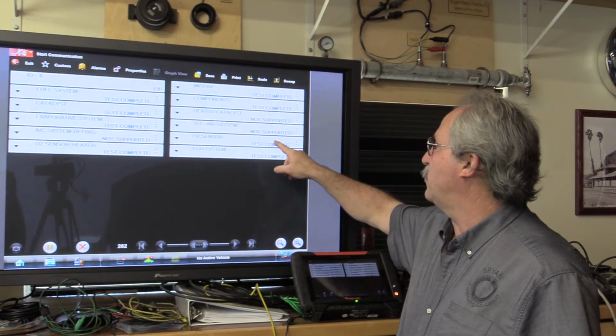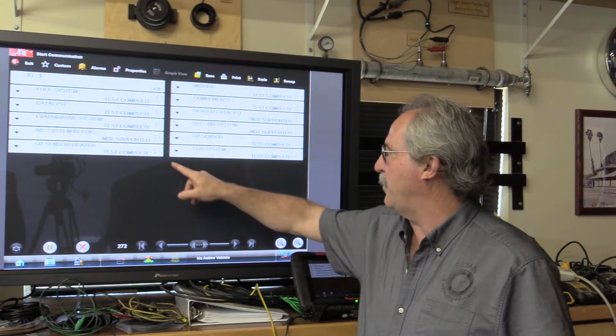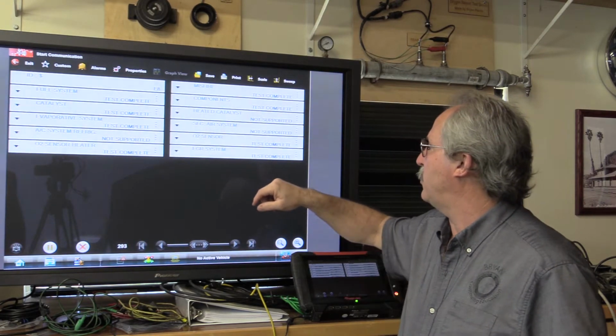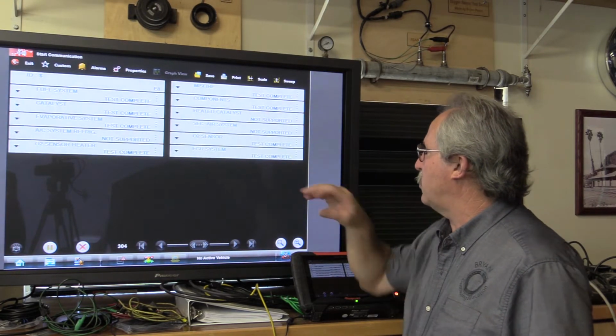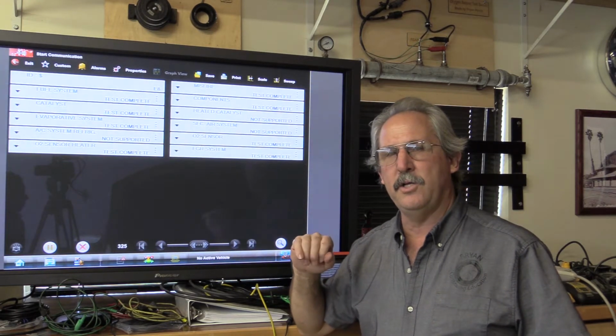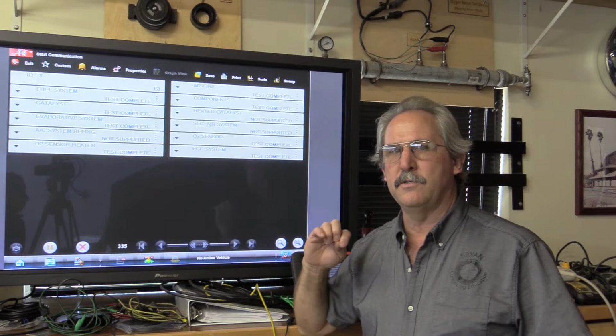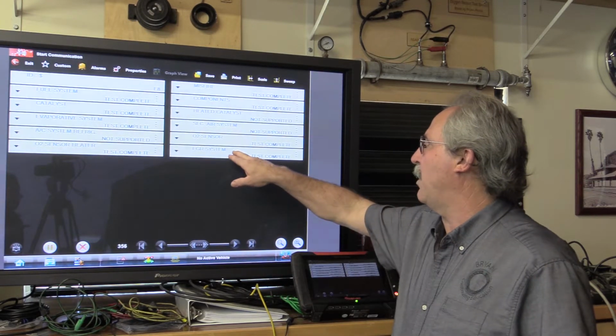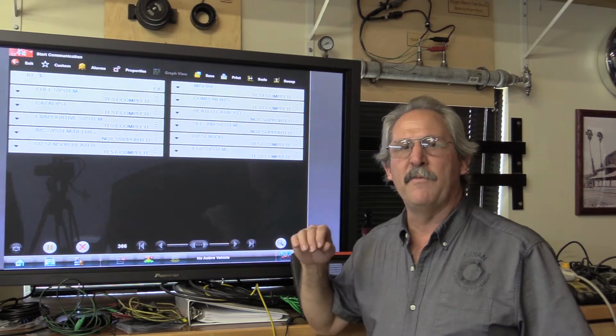Here I have an O2 sensor. This is O2 sensor performance. This is the O2 sensor heater. I have my catalyst, my fuel evaporation system, and then I have EGR system. And the EGR system on this is unique because this car does not have EGR. This car uses variable valve timing to perform an EGR function. Therefore, this monitor is really my variable valve timing monitor.